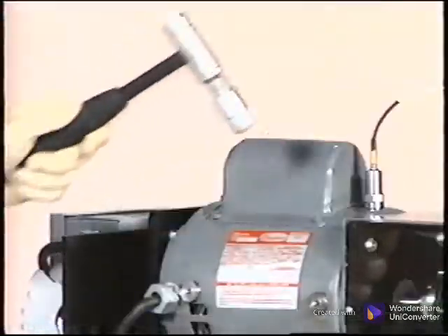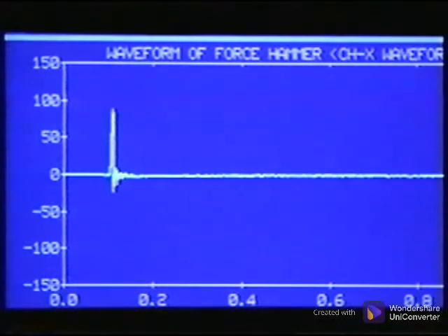An impact hammer is usually used for resonance testing, and the accelerometer response is measured to determine the resonant frequencies. In this case, however, we will only measure the instrumented force hammer and capture the energy of a single impact. A single impact imparts all the frequencies, but does not have any repetition.